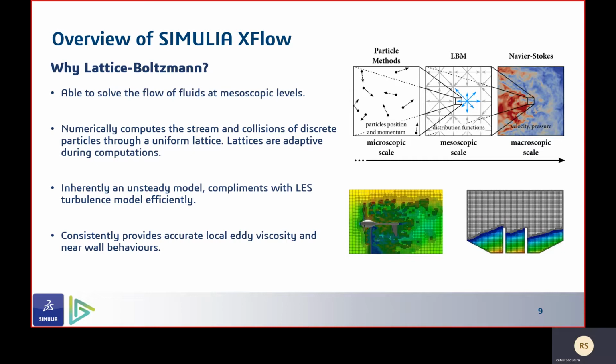Because of this accuracy, it's able to compute the streams and collision of discrete particles in those lattices. And these lattices, as I mentioned, are highly adaptive during the computation. So they move along with the geometry according to the current position of the geometry. As it is an inherently unsteady model, it actually complements very well with the LES turbulence models, unlike other solvers,